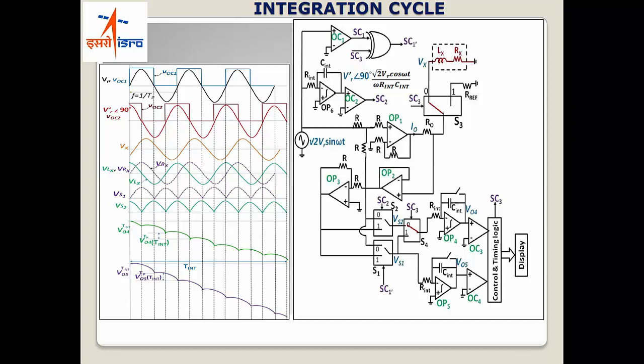Then what I do is I will use my switching waveform, the SC1 as well as the SC2 outputs, in order to switch this voltage, and I'll get two rectified outputs. This is just shown like this for ease of representation, but this is not the way it's going to actually look, because once you rectify this with respect to this particular waveform, it's going to look slightly different. Just for illustration, I have shown Vrx is going to be proportional to the sine portion, and Vlx is going to be proportional to the cos component. So you get a rectified output of this.